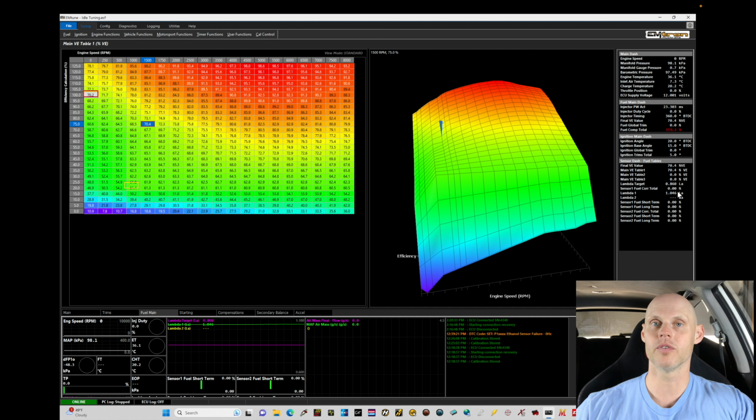I can't talk over this car here on the chassis dyno, on my mainline dyno right now. So we're gonna be talking about what I'm going to do for logging, and then we're gonna play it back and start to dissect the data log using a playback feature and using an overlay feature here in the table. It's actually quite simple. This is a better way to try to calibrate and tune, especially if you don't have a chassis dyno at your disposal.